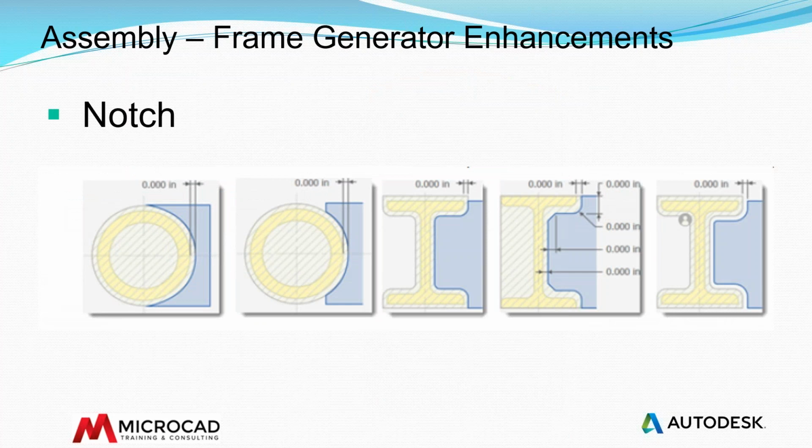The notch command is now a property panel, and in the new panel, you do not need to select an option to notch multiple members at the same time. Previously, it was difficult to create a custom notch. In this release, you can now specify the following: basic profile to set a single offset value, a custom iTemplate to set multiple offset values, and a custom profile, if available, use a custom notch profile saved in the Content Center family.